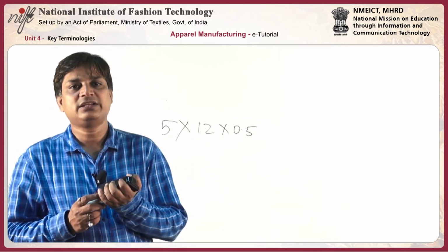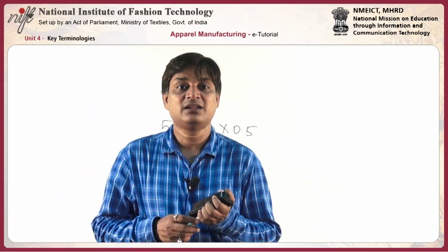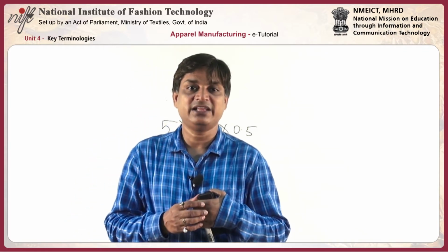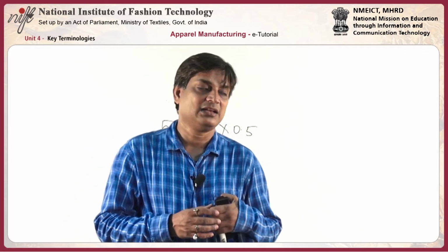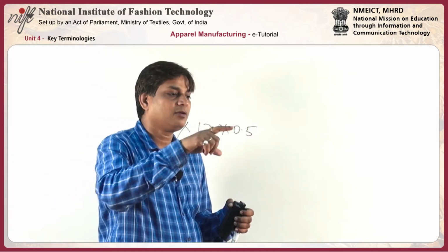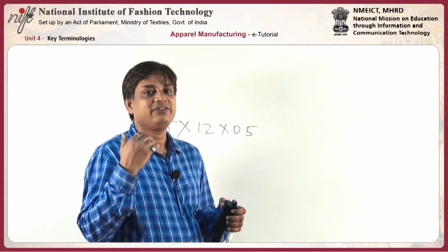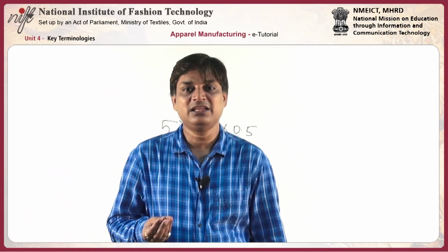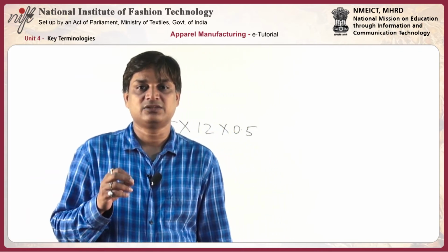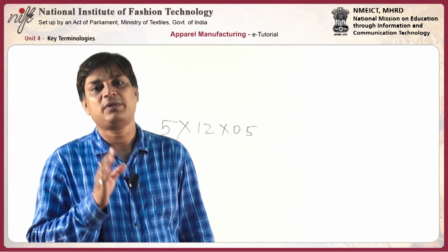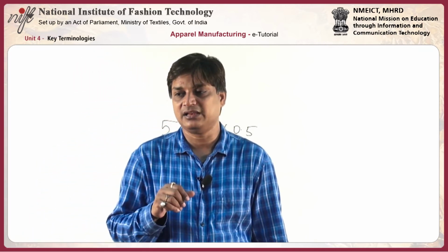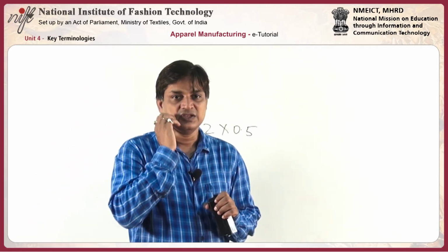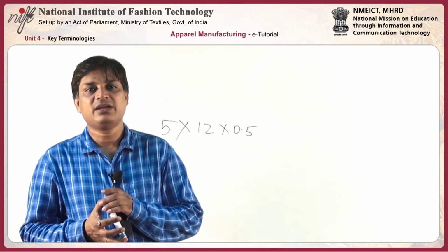The advantage of controlling WIP: when WIP is controlled, there are two cost areas that can be controlled, the investment in inventory and the ability to reduce the production cycle. If there is more WIP, the production cycle will also increase, and the investment in inventory will also increase. Investment is the money we have invested in raw materials. When we don't move the goods through the plant quickly, we are affecting cash flow directly. So more WIP in the line blocks the whole cash flow. So we have to manage the WIP.